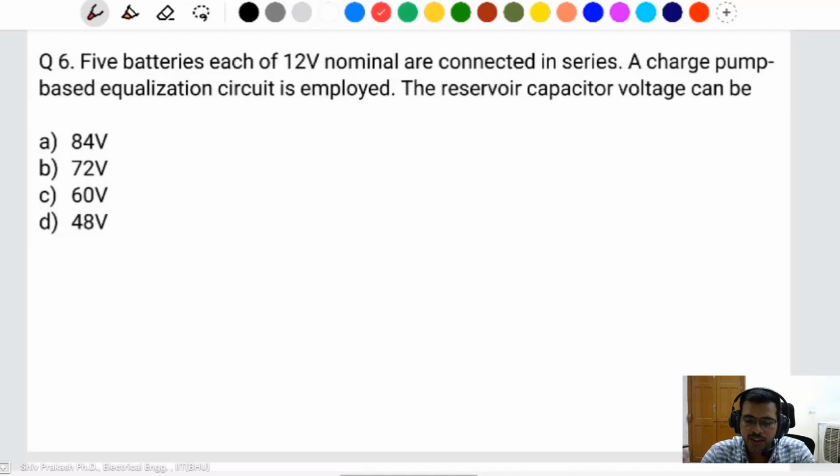If you made at the same laboratory, same material, but some of the error is coming in all of the batteries. That's why the capacity of all battery is different. Minimum difference or maximum difference, it depends, but some of the differences also occurs between the two batteries. That's why the charge equalization is the important in series connected battery.